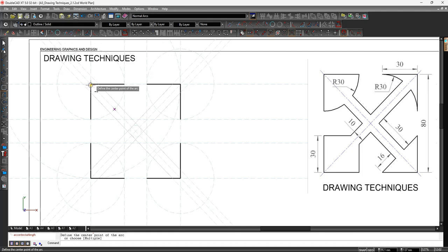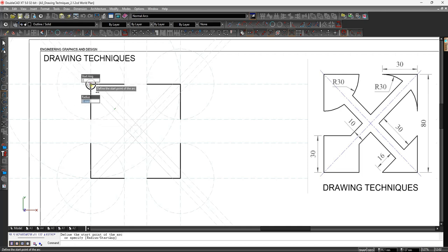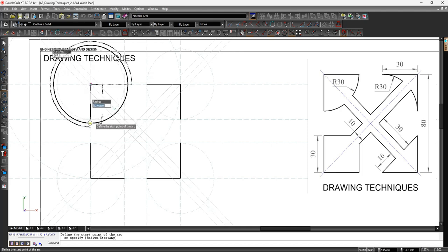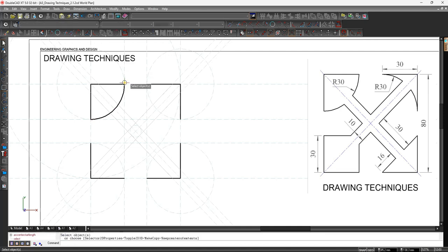And on my reference point there I'm going to duplicate what I see on my reference image, and please remember when you draw an arc it will always go anti-clockwise. So I'm going to start my reference there, and then I'm going to click on this snap at the end of this vertex, and I'm going to swing it all the way upwards anti-clockwise, and then snap onto that point. Now I don't need that full circle, I want that part there as an open part as per the reference image, so I need to clear that.